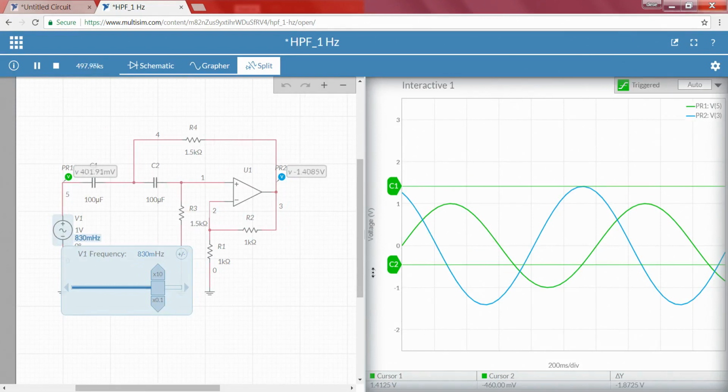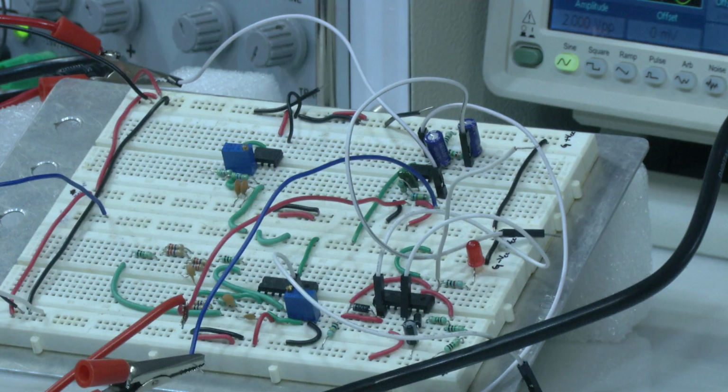What we do is that we will look into the board. We have already done the same circuitry using our breadboard, so we use the other part of the TL082. Previously we have seen the low pass filter, now we will see the high pass filter on the same op amp, just next to that, but we are using the first side of the op amp in this case.